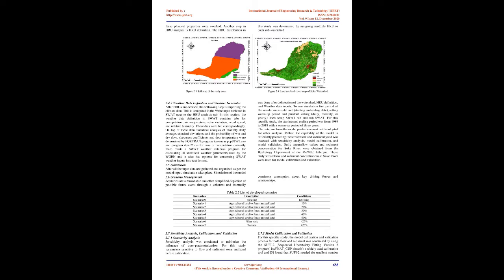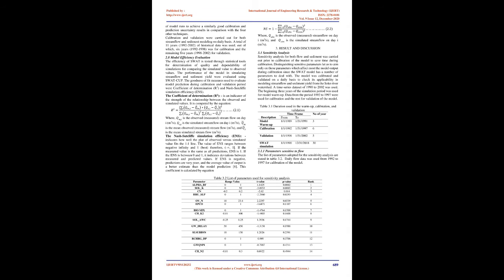2.5 Simulation. After all the input data are gathered and organized as per the model input, simulation takes place. Simulation of the model was done after delineation of the watershed, HRU definition, and weather data inputs. To run simulation, first the period of the simulation was defined, starting and ending date, setting warm-up period and printout setting, daily, monthly, or yearly, then set up SWAT run and run SWAT. For this specific study, the starting and ending period was from 1989 to 2018 with a warm-up period of 3